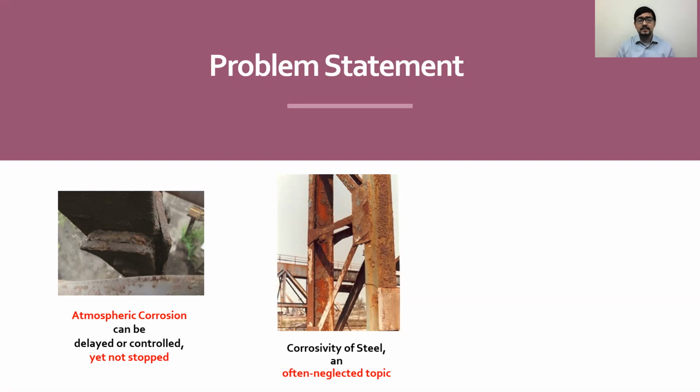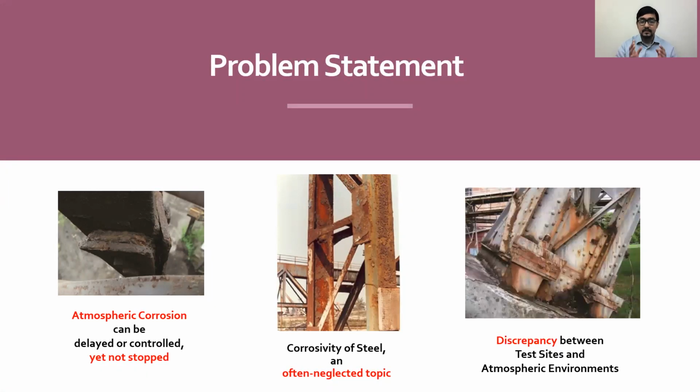We all know that this humidity level is not constant. It depends on numerous factors such as the properties of the corroding materials, the hygroscopic nature of the corrosion products, and most importantly, when there are pollutants in the atmosphere. However, if we look back, we can see how little time was spent on atmospheric corrosion studies compared to the other topics related to steel structure design. And surprisingly, the atmospheric exposures encountered at these sites are completely different to that of the test sites used for evaluating corrosion.